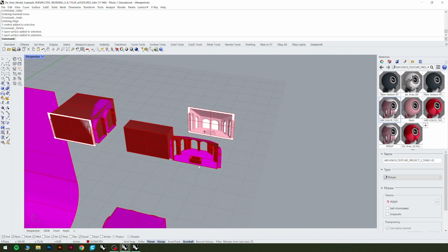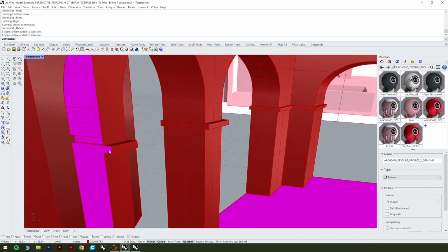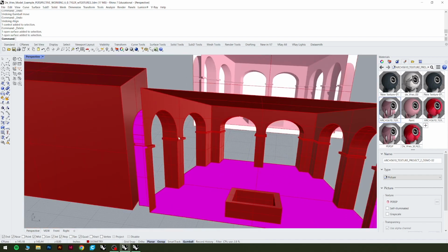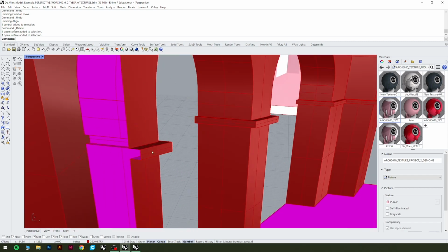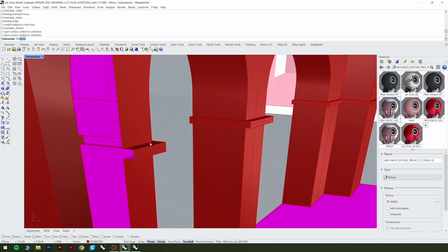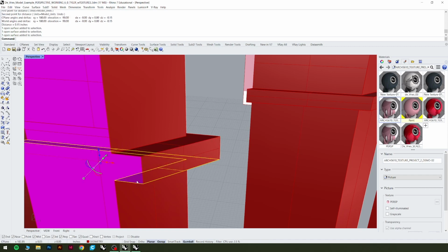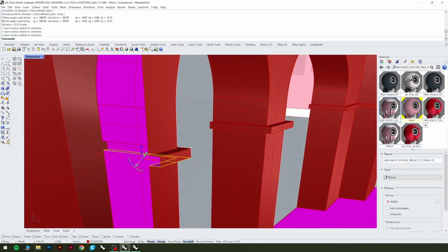One thing that I didn't mention, and I know this is already at 20 minutes, but these kind of detailed things in the columns, a lot of things like that, you just want to eliminate those. I know in Blade Runner, things are pretty minimal, so you might not even encounter this. But if you do have fussy little details, just remember, go look at that with the distance command and see what the size is. Because at 0.15, that's not so bad. It's larger than 1/8 of an inch, but not by anything significant. It's maybe a 32nd larger than 1/8.